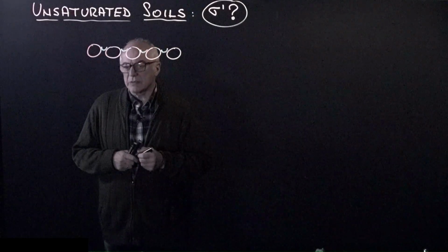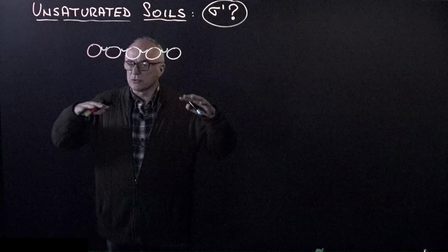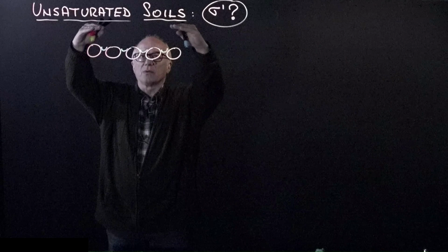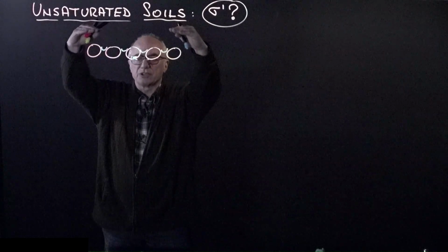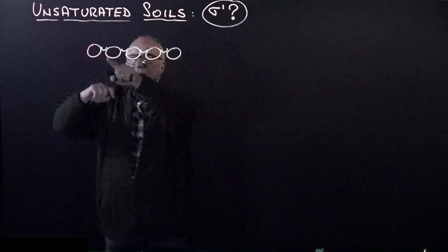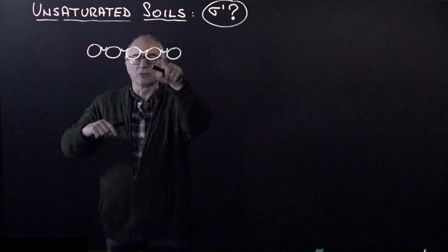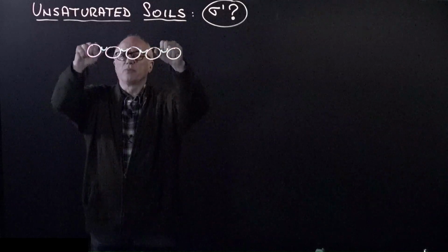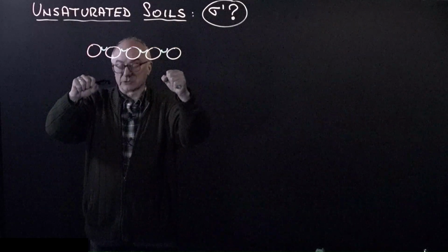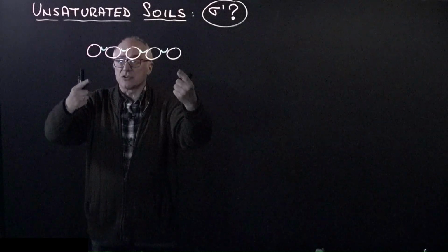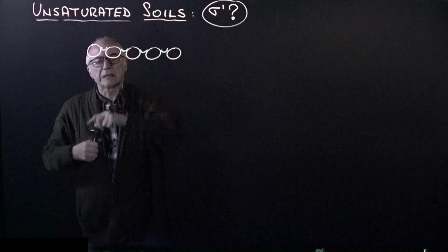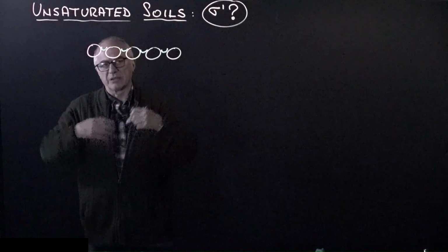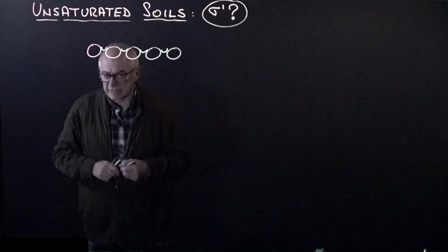When a soil begins to desaturate, or let's be clearer, when the water boundary reaches the soil, menisci hang from the soil because the water likes to wet the soil and pull the soil out or down. In addition, they put the water in suction, so the water pressure decreases below what would otherwise be hydrostatic.